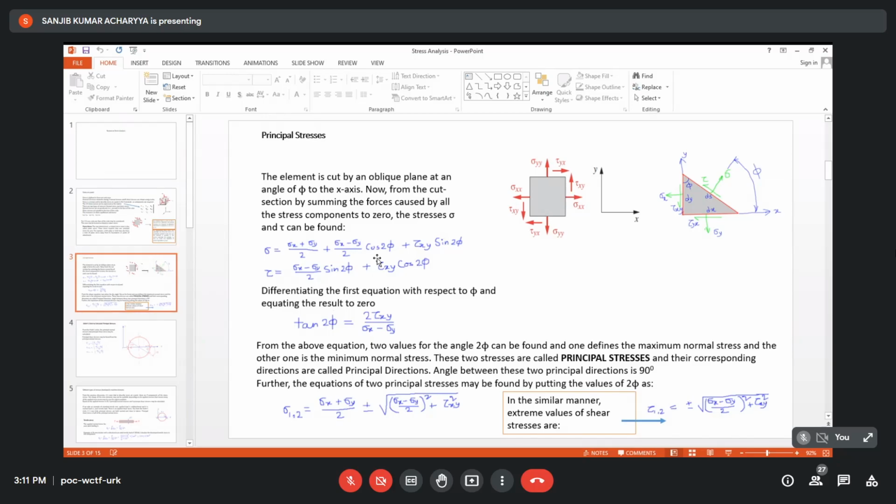Obvious, because designers are responsible to satisfy the strain, and it is obvious that if the maximum stress developed within the material is kept below the permissible stress of the material chosen, all the points will sustain the load, because in other points stresses are lower. So designer interest, if a member is subjected to this kind of loading, where the maximum stress can be developed, if I can get the expression of that maximum stress, my requirement is over. Do you agree or not?